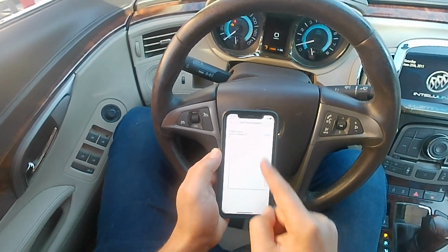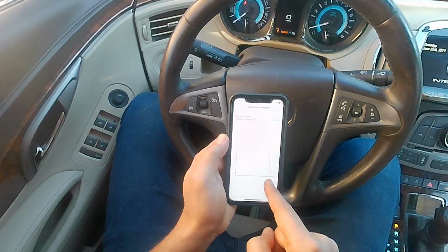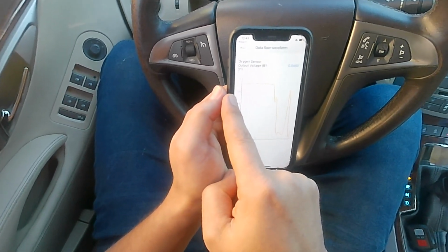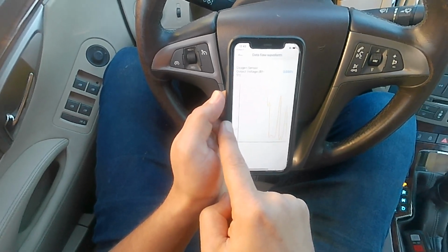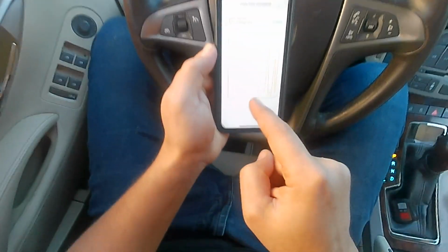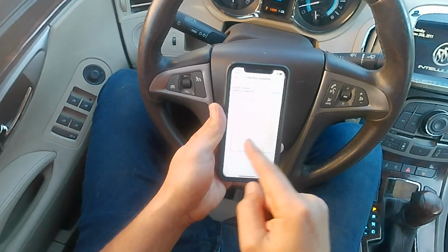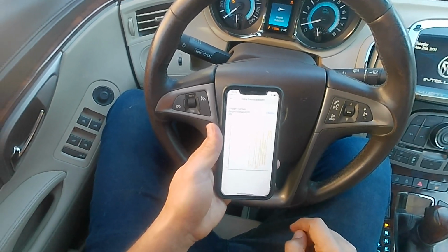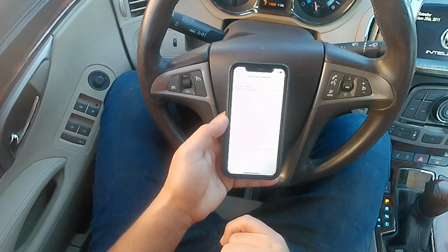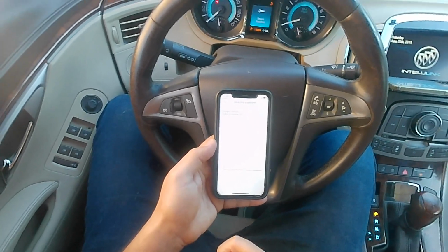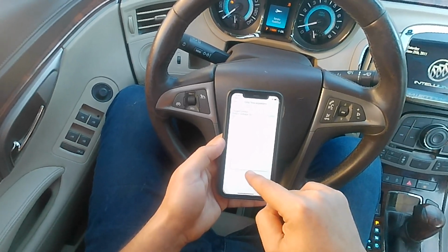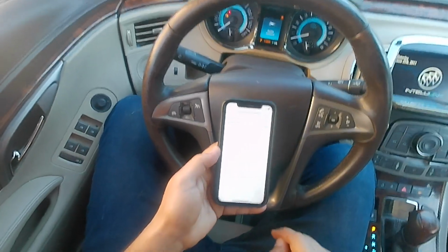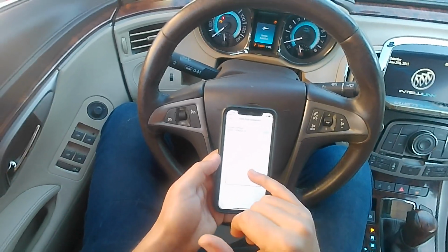This is bank 1, and then it's going all the way down to 0. We are here at 1, so this is 0.8, 0.5, 0.4, 0.2, and then to 0. So for me, this is an indication. If you can look at the warning over there. So what I'm gonna do is I'm gonna go ahead and see, and then every time it goes to 0, that warning, service StableTrack warning is coming back on the dashboard.